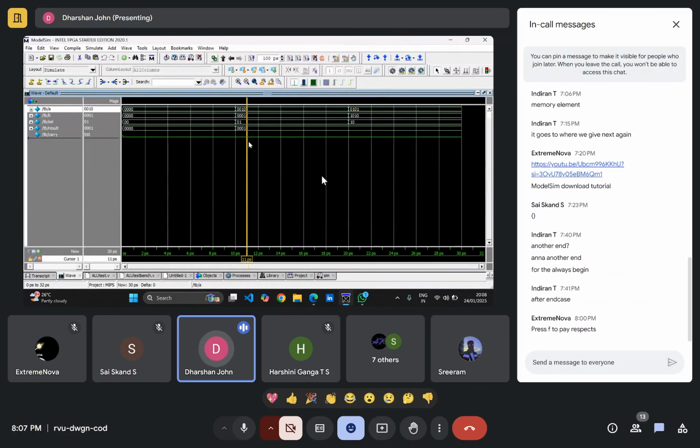It usually varies based on the architecture itself. In this one we wanted to give you a basic implementation. A real ALU will have many more instructions and many more things. It will have not only the result output; like the carry we look at, you'll have a zero flag, and you'll have something called overflow and so on. All those things vary from instruction set to instruction set. We just showed you the basic implementation, so you'll have really good hands-on experience. Now that you've done it, you got to know where the chances of making mistakes are.